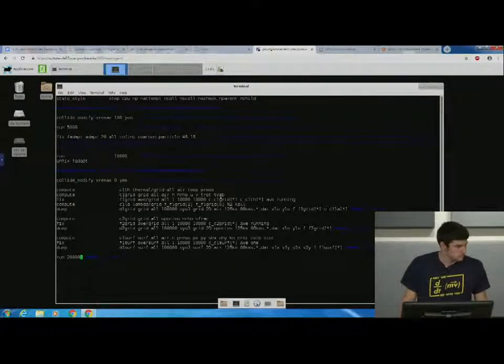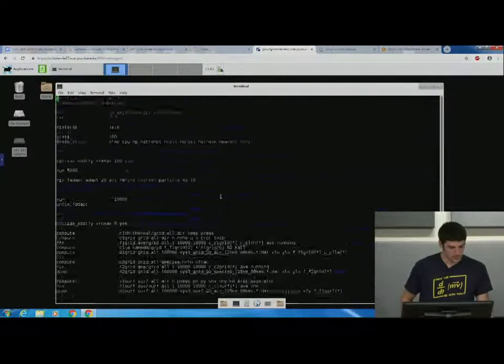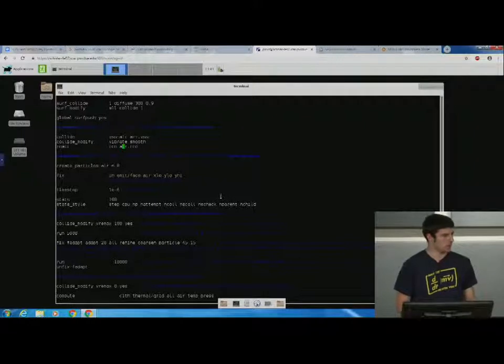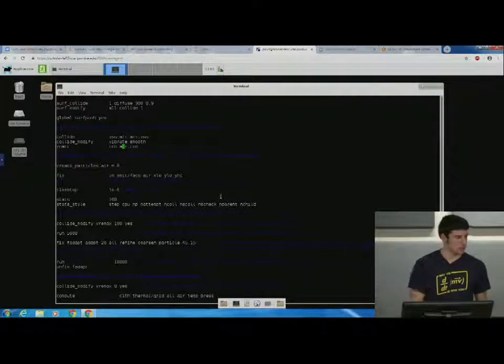I'm not sure if you mentioned it or not, but where do you define your reactions? Reactions are defined here. It says react according to the TCE model, total collision energy, and the details are defined in this air.tce file, which is what we'll look at coming up. So basically in terms of the reactions, unless you're really looking to change the reaction rates, which I think would be a very big problem to do for this project, you just copy this air.tce file into your directory, and you just stick with this file would be my suggestion.